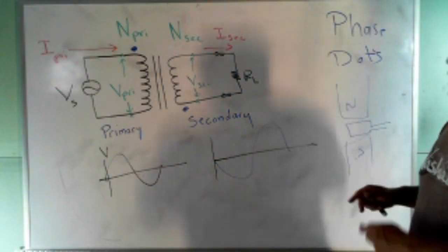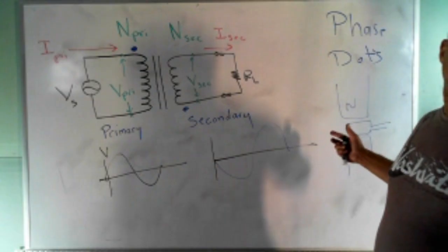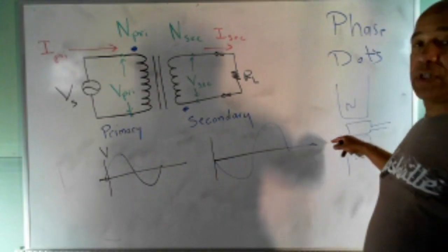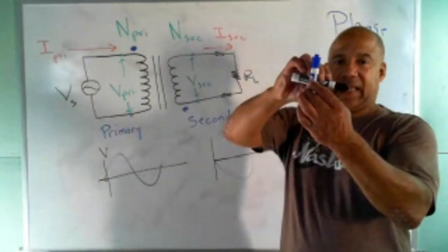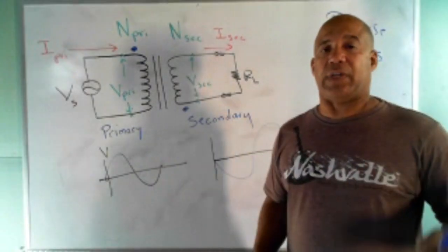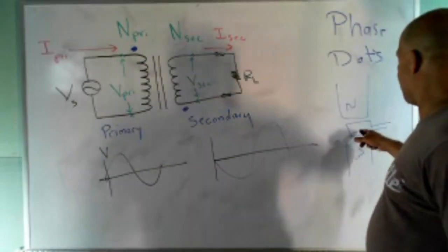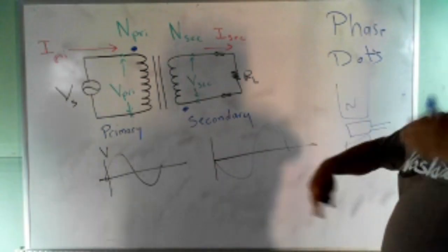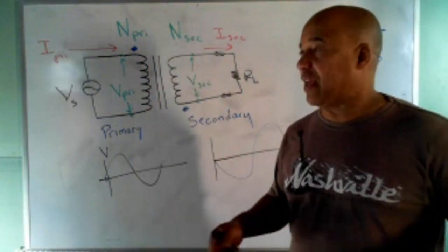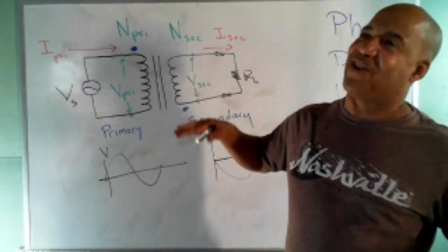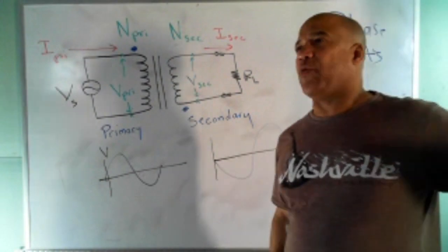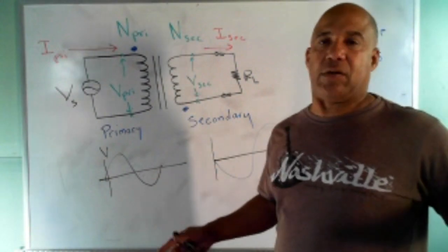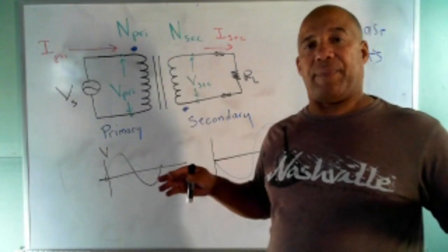Well, it turns out that you can have as many coils in there as you want. You can have 2 coils in there, maybe one like that and one like that. Then you have 2 sine waves produced. They call that 2-phase. Or you might have 3 coils in there that you rotate. They call that 3-phase. You can have as many coils as you want. It turns out that if you get over 3, then it becomes more impractical because they usually stop at 3.